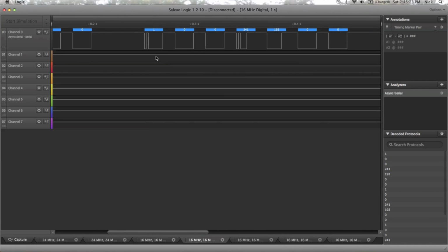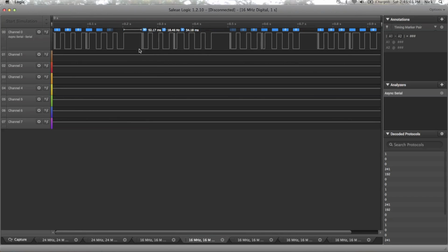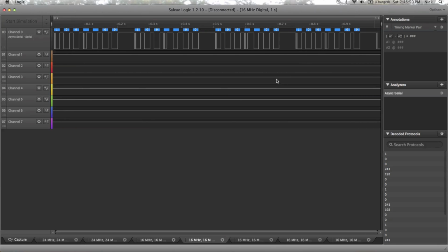So if we come over here, we have a 10024119200, and one of these is for the power comfort switch. I found one was for the TPS sensor. I think one is the speed sensor, and then we got some other stuff. The last 0 is an error, so if it goes 1 or something else, it's different error codes. I don't think the 1 changes, so that might help us out, but this one makes a lot more sense. You get all your bytes, and then a space, and then all your bytes, and it kind of makes sense.